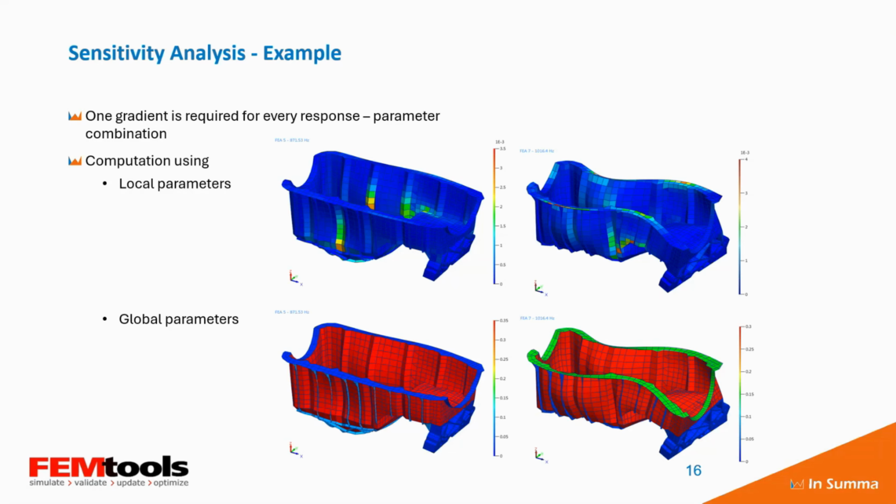Some elements will have multiple parameters that you can select. You can select elastic modulus, rho. You can select plate thickness. So there are different possibilities. You can have a huge number of parameters, a function of the number of elements, and then go down to only one or two global scale factors, and anything in between, depending on how you group elements.